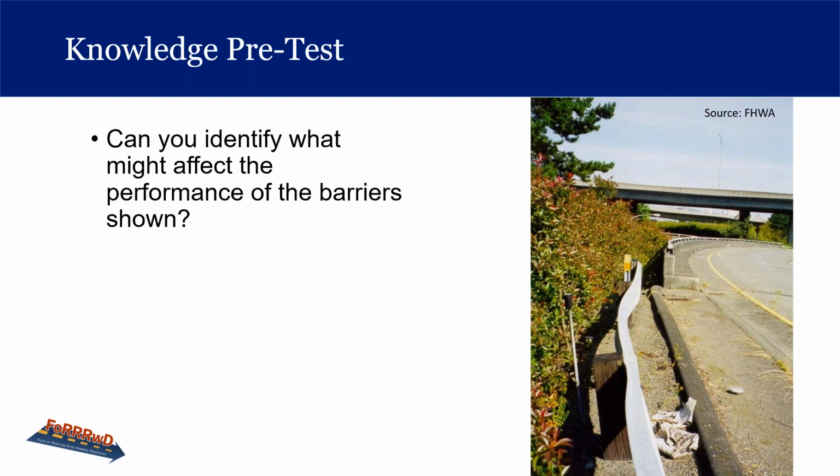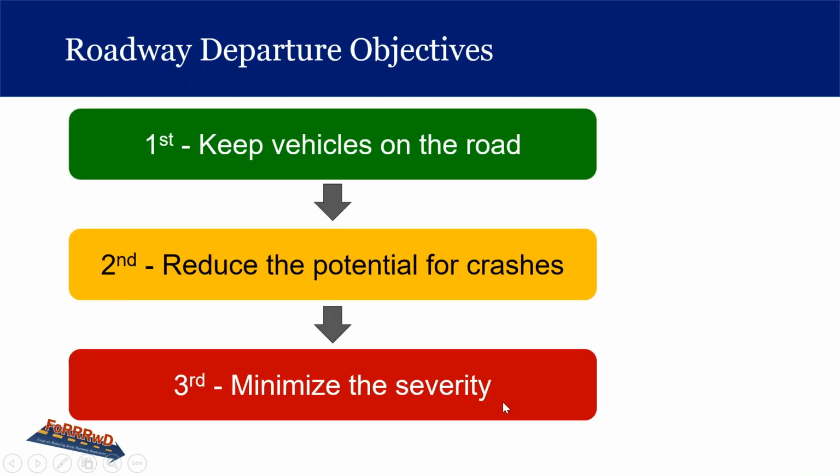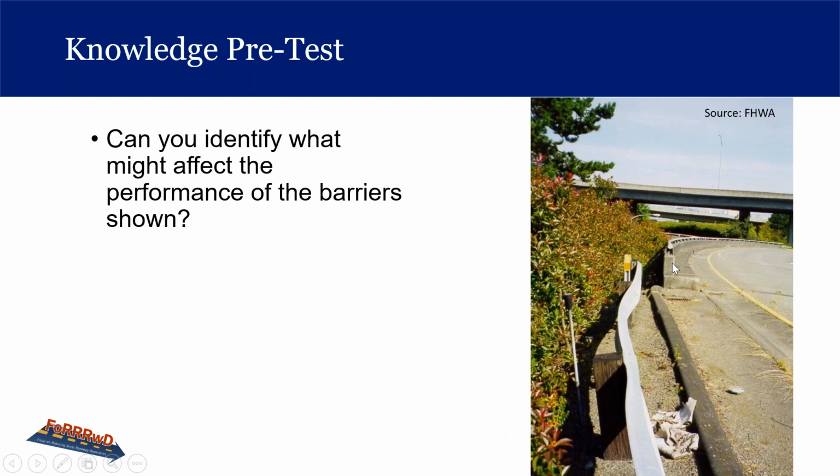Okay, so this picture was taken in Tacoma, Washington. And so what we see is some old guardrail in the foreground. And it says no block and 12 feet 6-inch post spacing. May not contain the vehicle. The curb is in front of the guardrail. See this curb here? That's a curb. So if your tire gets over that and caught in here, it's just going to guide the car on up to the crash into this end treatment here.